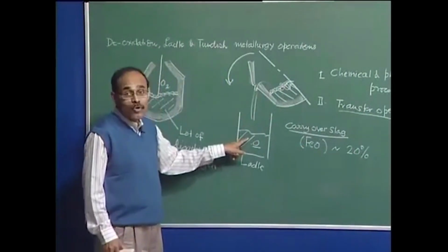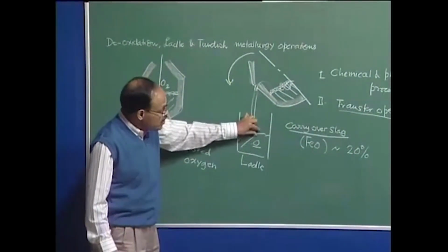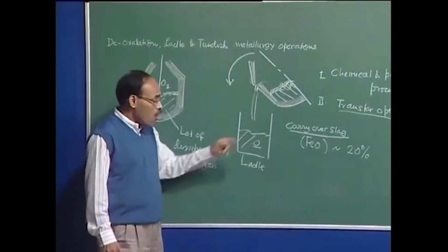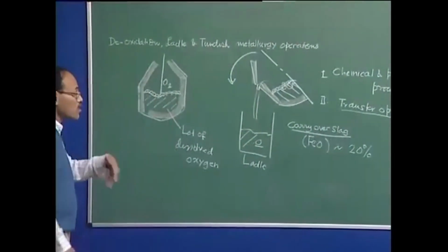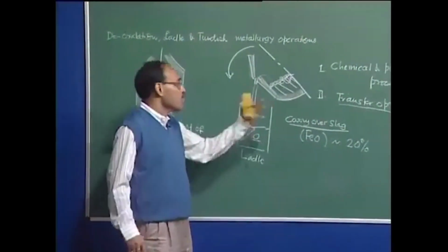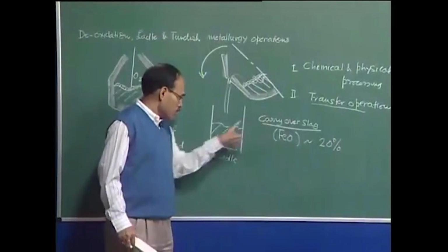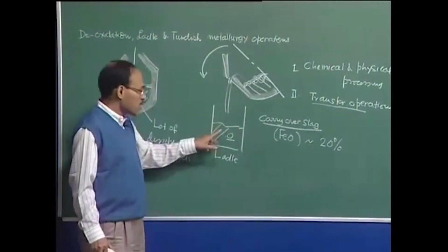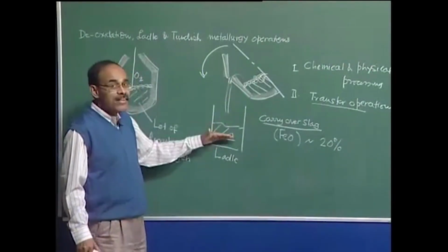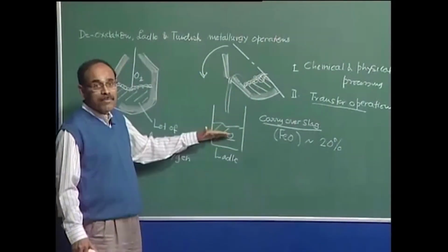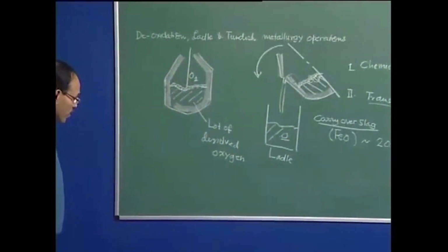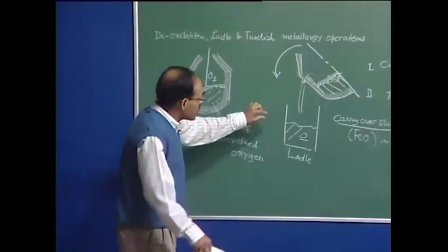We are not going to entertain any amount of this slag coming here, because we are now going to remove oxygen, which is essentially a deoxidation or reducing operation itself. So the carryover slag, as we advance, we will see, influences adversely the properties of the steel. As a result, all subsequent refining reactions beyond the primary steelmaking vessels, which are going to be carried out in a ladle, are actually going to be done in the presence of a new slag.